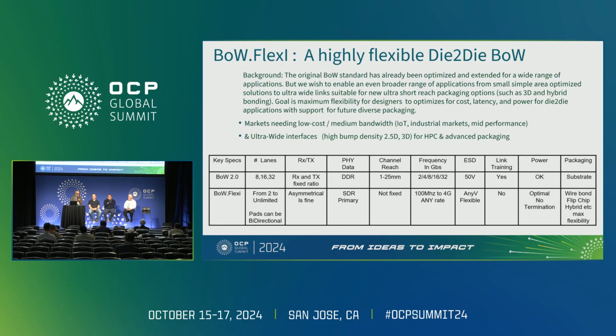So instead of a 2 nanosecond latency that everybody is struggling to meet the spec, here if you're running at 3.5 gig, just like UCIe 3D, your latency is half a clock potentially, right? So it's very, very low latency. Interop becomes really, really simple, right? So there's a lot of advantages. We can support older nodes and mix those with advanced nodes in a seamless way. So that's the basic idea.